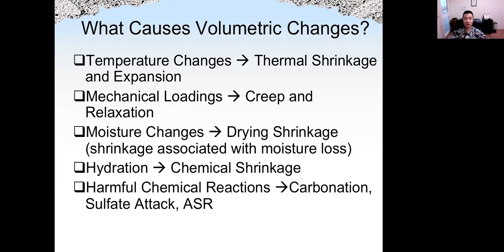Temperature change. Higher temperature, the concrete will expand. Lower temperature, concrete will shrink. That's true for almost all types of materials. Mechanical loading. If the concrete is under load, then it will creep, depending on whether it is under compression or tension.